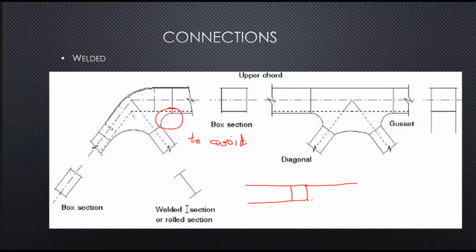Let us say I have a weld here, right? One weld. Now, if I draw the stress diagram for the member, ideal member, this is my stress diagram for the member, right? Now for this joint, at the joint it shoots up. It is because of the discontinuity in the weld, the defects in the weld.